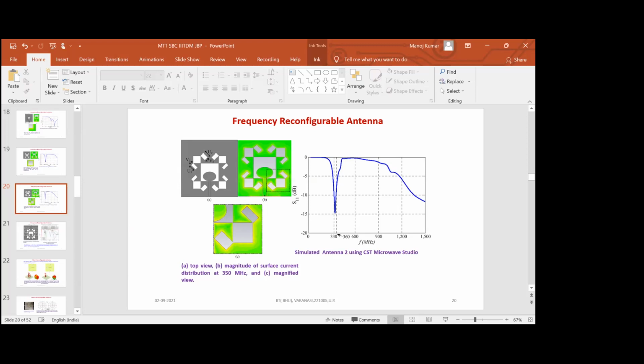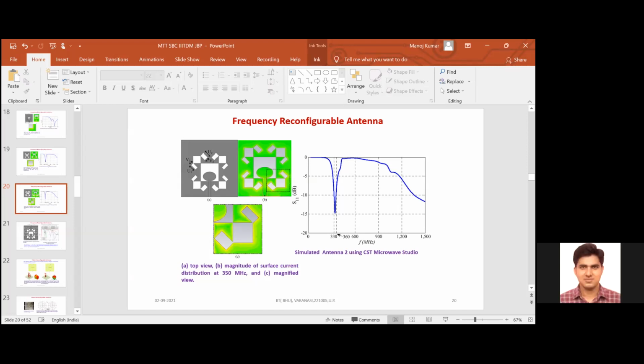Have you seen any microstrip line in the millimeter range? If you consider the width of the microstrip line in the 100 gigahertz range, you can choose low loss material, don't worry. So you can see the width of the line. What is the width? It's very thin. It is not visible. So we need sophisticated machines, and it will always be printed in chip form. You can use the same machines for printing the biasing circuitry.